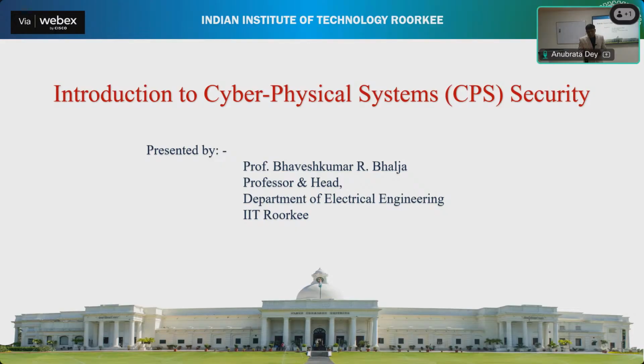And whenever the mitigation part comes, of course, for 61850, maybe client-server communication, or for others, as Professor Sidhu indicated, we can use cryptography. That means we can use either public-private keys, digital certificates, or anything else. But the major issue with all that cryptography is that it is going to add time delay, and nobody is going to talk about time delay. Why? You know that cryptography was invented a long time ago, 2 or 3 decades ago.